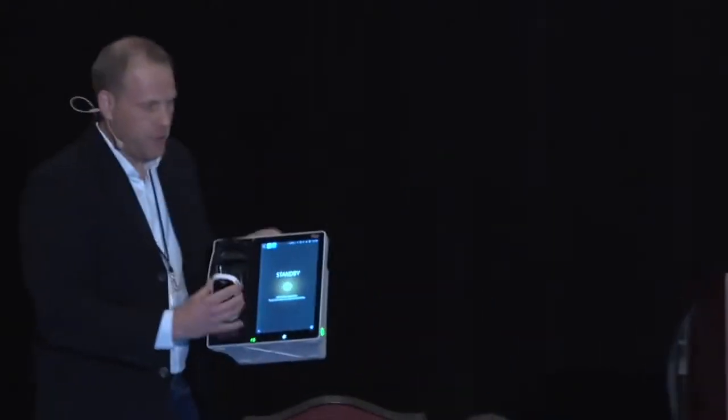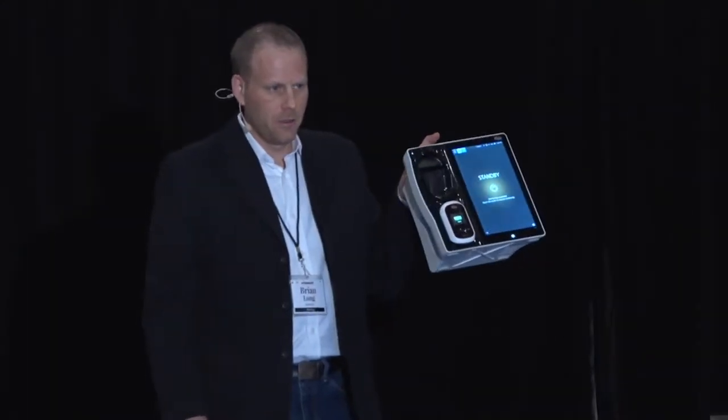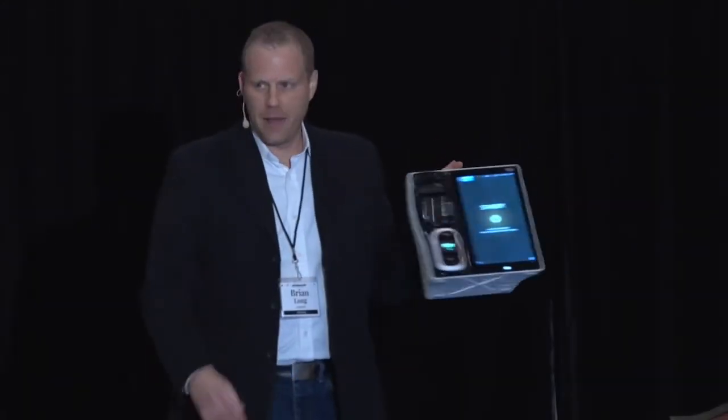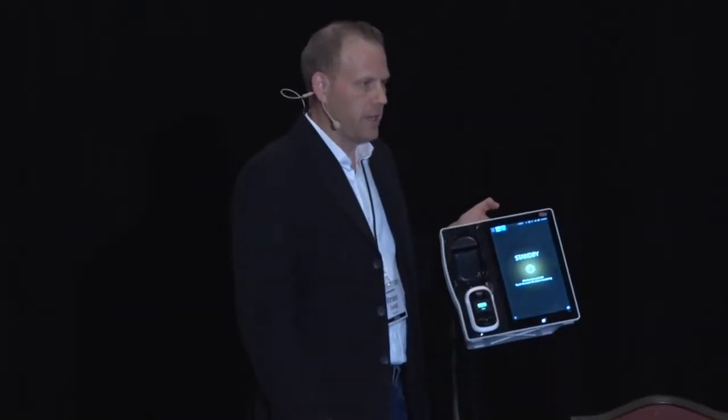The last one, which is kind of interesting and cool, is what's called out-of-band pairing. Out-of-band pairing basically authenticates a device through some type of physical connection. So, for example, in our medical device, we do our out-of-band pairing as simply as this. You take this device, connect it up. You probably didn't hear it, but there's a little beep. And now this device is paired with this device, and it's authorized to communicate with it.